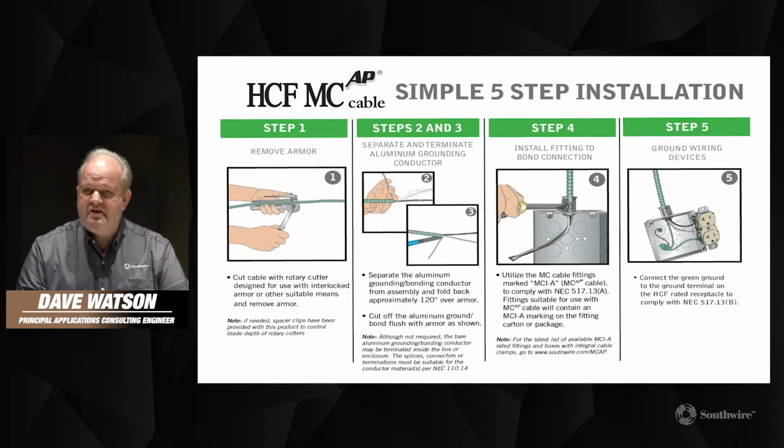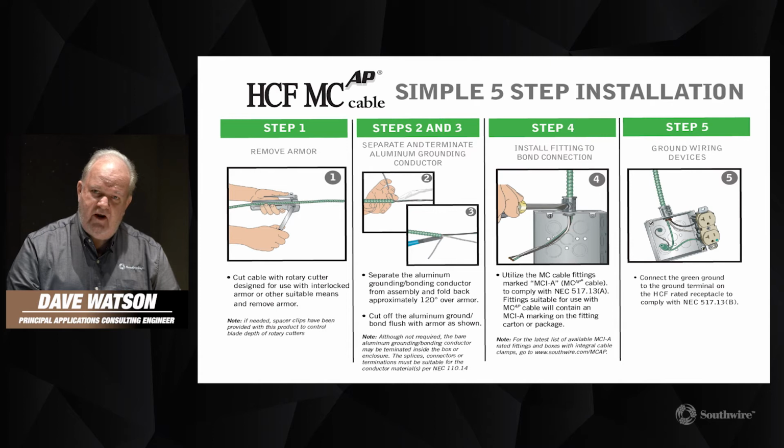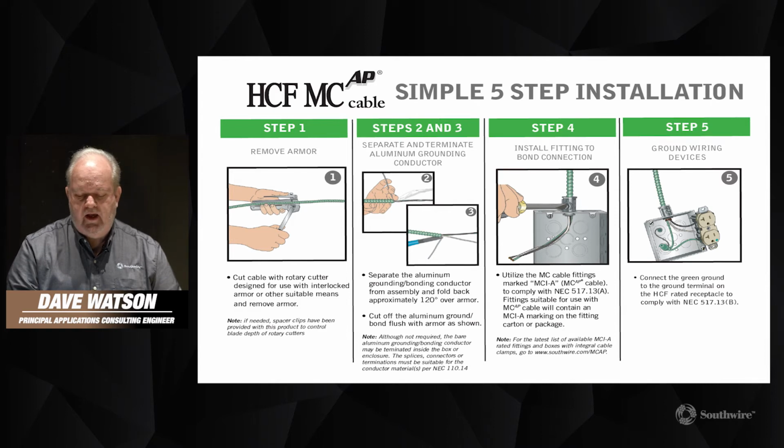The 5 steps of installation for this product. Step 1 is removing the armor. This shows a tool called a rotosplit, which is a very handy tool to use for removing the armor. Steps 2 and 3 are to separate and then terminate the aluminum grounding conductor. So you separate that from the other conductors in the cable, and then you cut it off flush with the armor. You do not wrap it back around the armor like you would do with a type AC cable. This is a critical step. So cut it off flush with the armor.